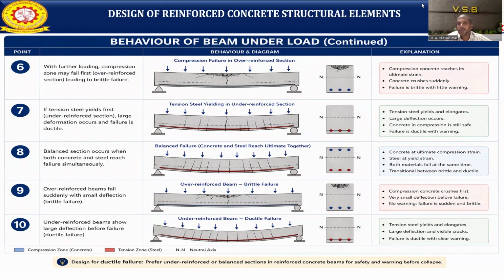It's one cause of the failure. The concrete crushes suddenly, in the topmost zone above the neutral axis. It will be crushed suddenly. This failure is called brittle failure, with little warning. It gives only a small warning, so it will be a sudden failure.